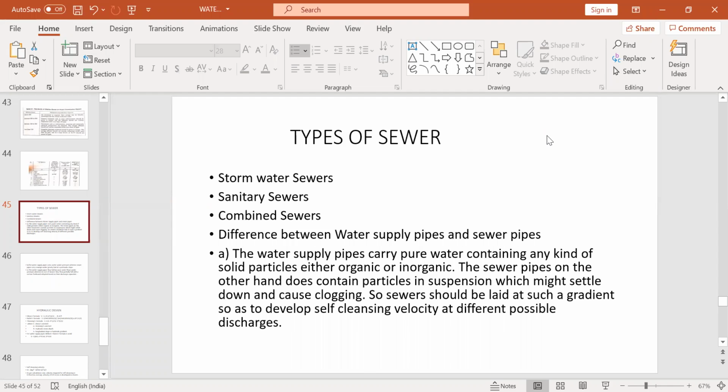Okay. So that conveyance is with the help of a conduit called a sewer. A sewer helps in the conveyance or the transportation of the sewage or the storm water, whatever you may call it, to the final treatment plant. After collection of all the sewage or the storm waters from the household, it will carry this sewage in a conduit and bring it to the treatment plant. So that portion of this conveyance through a conduit is the sewer.